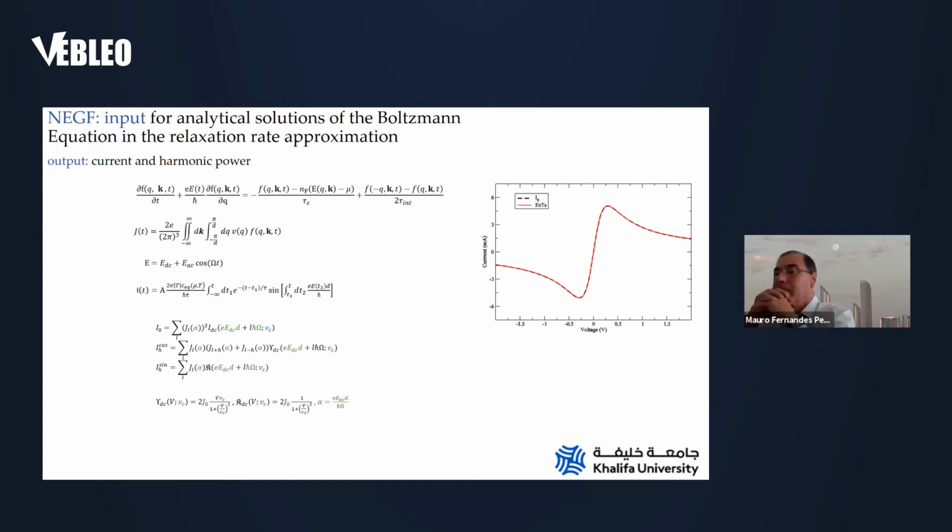If we have perfectly symmetric current voltage, if we have the same kind of scattering mechanisms for positive and negative voltage applied to the system, we have a completely antisymmetric current voltage curve, which is similar to what Esaki and Tsu predicted many years ago. The difference is that we can calculate it. So we know what these points here are, for example, we know what the peak of current is, and we know what the characteristic voltage or energy of the system is that characterizes the negative differential resistance range, which is here.